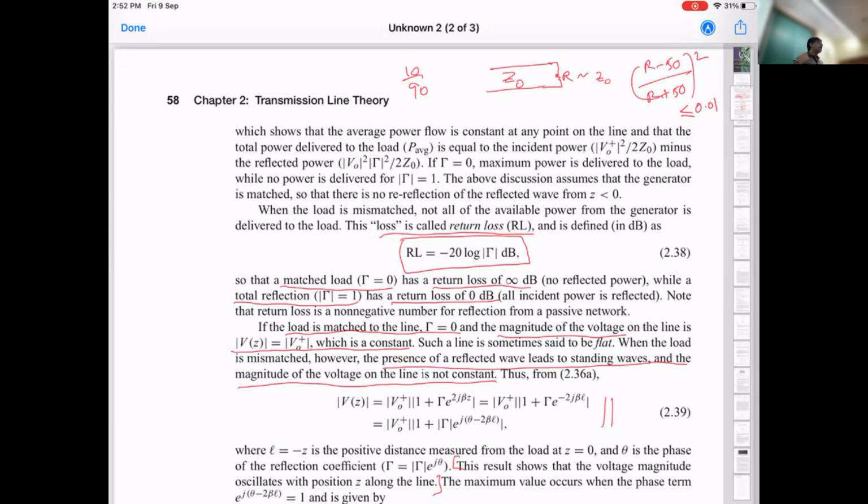So that power can go back. So there are actually special devices which prevent the signals going in the reverse direction from actually reaching the source of the signals, and they send it to another place where it's safely dumped. So here, even 1% of a large number could be a significant amount. So these are just examples where the context really depends. But this idea of return loss being 20 dB or less is valid for most typical scenarios.